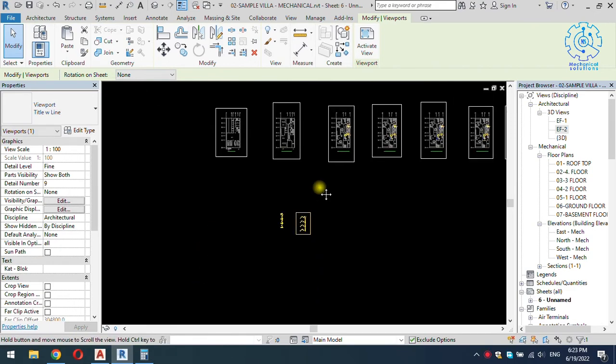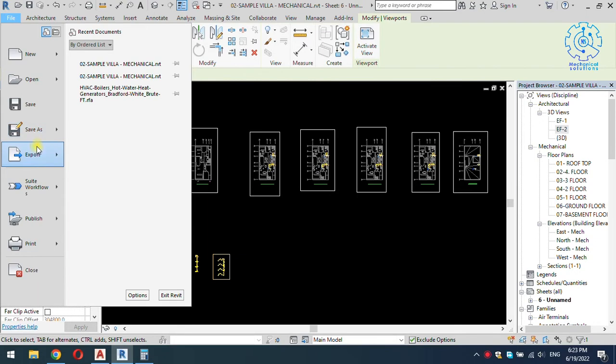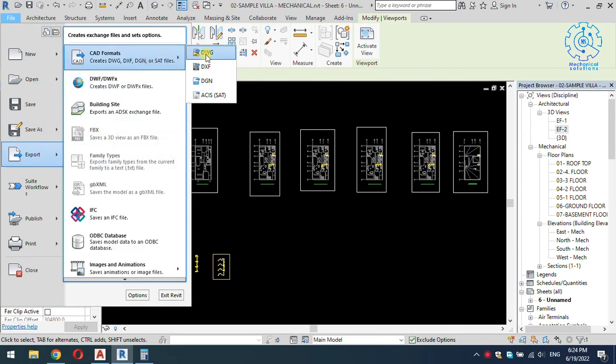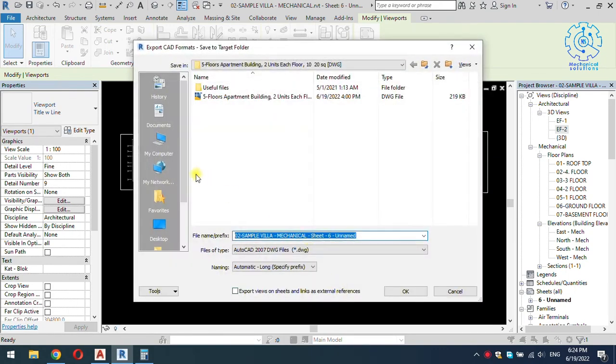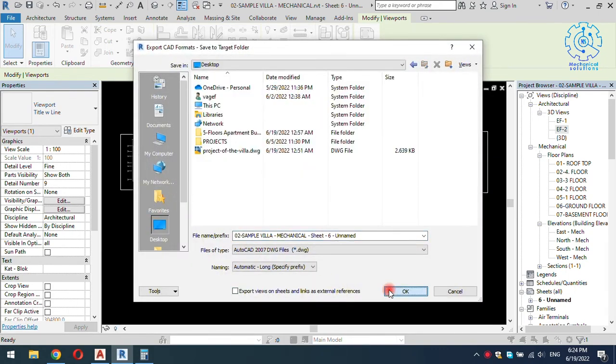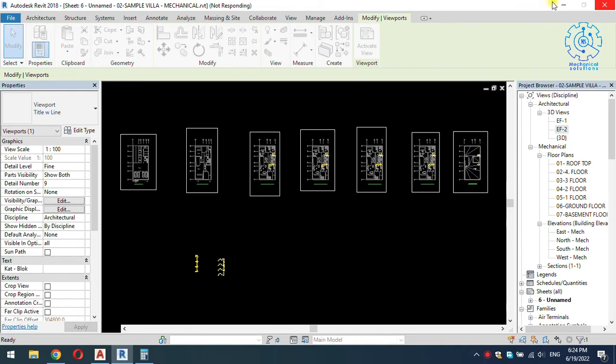So now I'm going to export, file, export, CAD formats, DWG, and next, desktop, okay, and I wait for my export to finish.